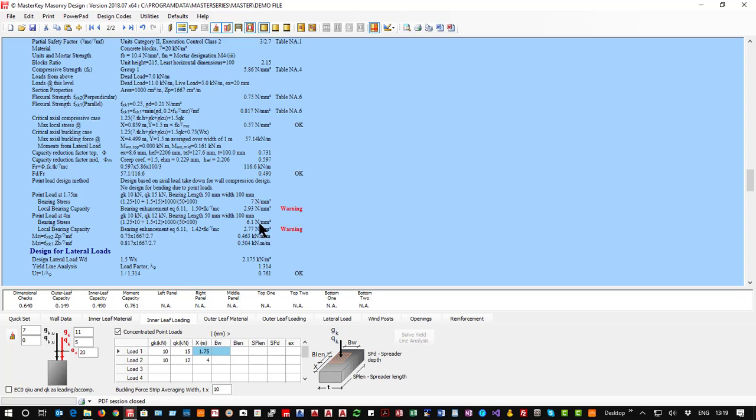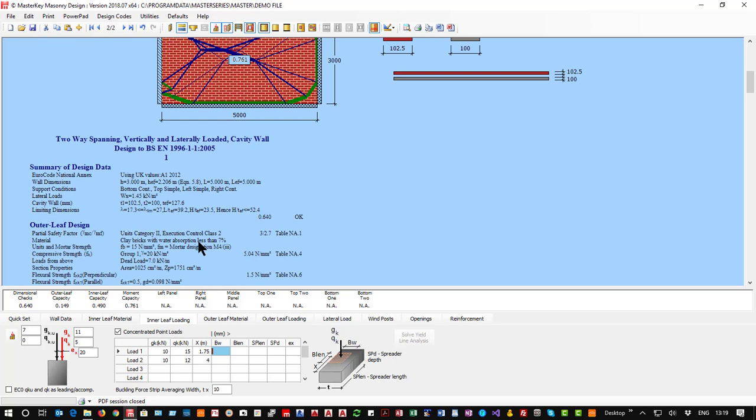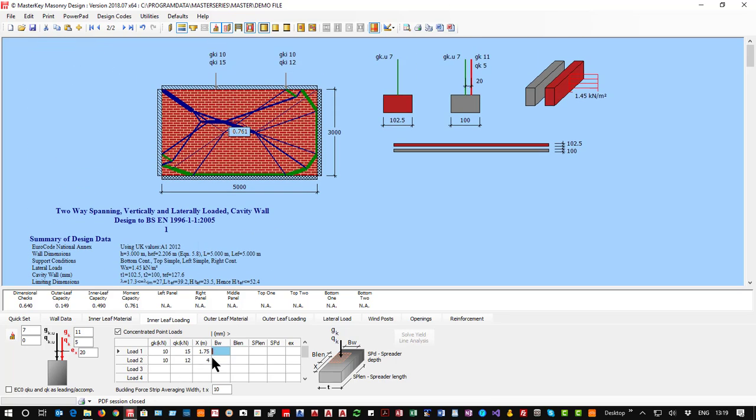So what can we do? Well, what we do is we put in some sort of padstone and we think about it. So this padstone, well, first of all, we would probably say, no, the point load isn't over a minute point, but is over a length and a depth into the wall. So it's going to be spread over 100 by 100 millimeters. So these now are all millimeter dimensions.